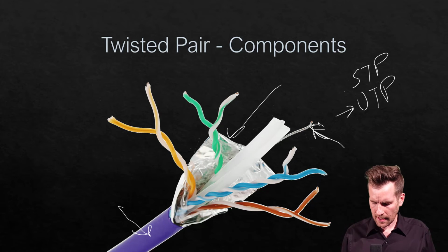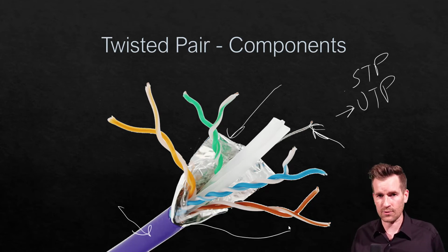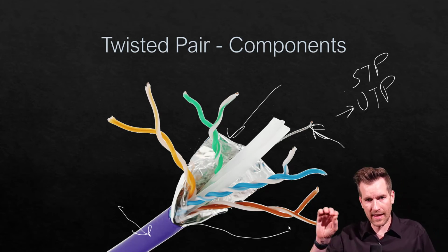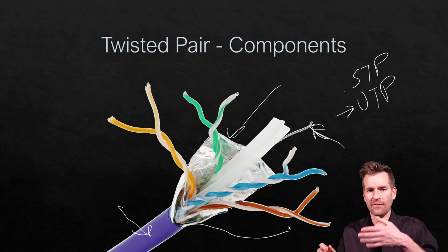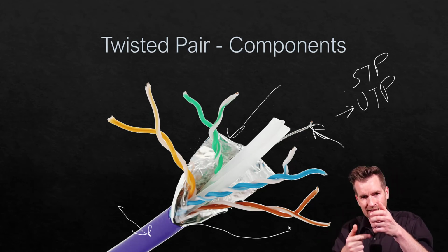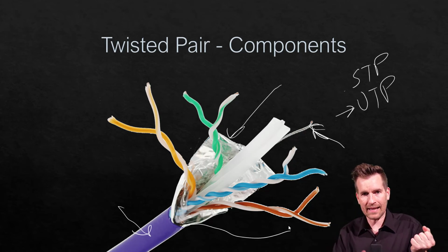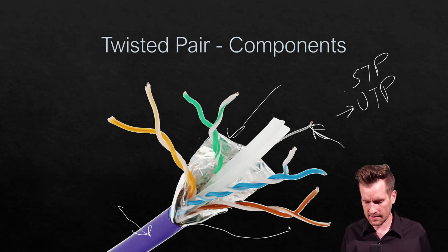One other thing that you'll see every once in a while, or a lot of the cables will have, is this ripcord. It's an extra little thread that comes out of the jacket. And what it's used for is to take off a big chunk of that jacket, meaning that you can grab hold of that and pull on it, and it will slice down the jacket lengthwise, and then you can peel that back and cut it off. So it's a quick, easy way to take the jacket off of a large section of this cable.